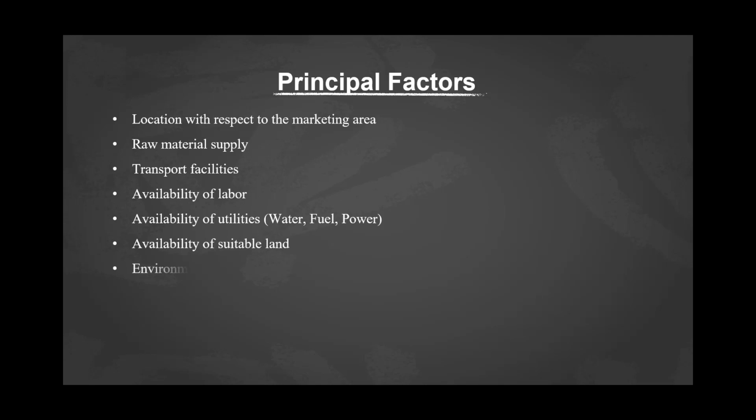Then we have environmental impact and effluent disposal. All industrial processes produce waste products, and full consideration must be given to the difficulties and cost of their disposal. The disposal of toxic and harmful effluents will be covered by local regulations, and the appropriate authorities must be consulted during the initial site survey to determine the standard that must be met.